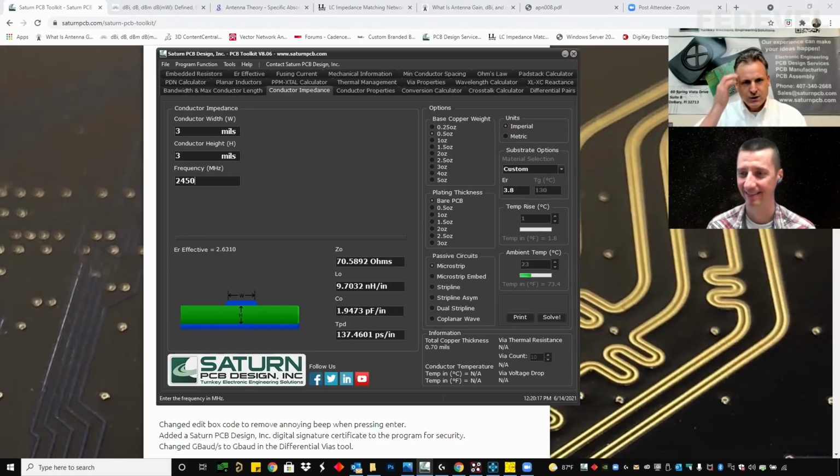So to answer your question, are they accurate? I've personally spent thousands of hours on this thing, going over formulas. Most of them I'm very happy with. There's a few out there that I'm still not 100% sold on, but without an EM simulator engine, it's as close as I'm going to be able to get with these formulas, because some of these formulas are just not accurate with every single geometry out there, which is what I've noticed. The microstrip I find to be pretty accurate.